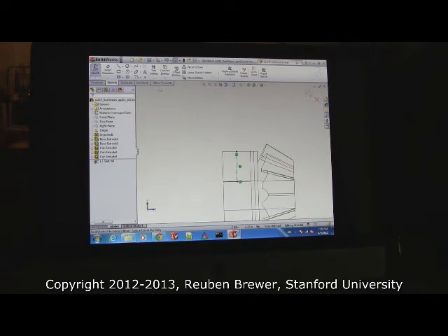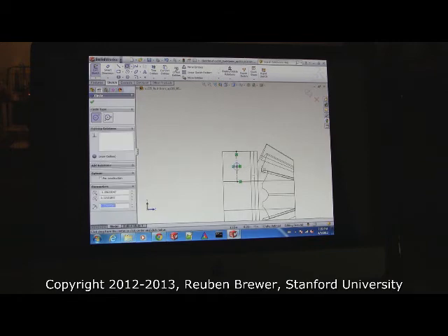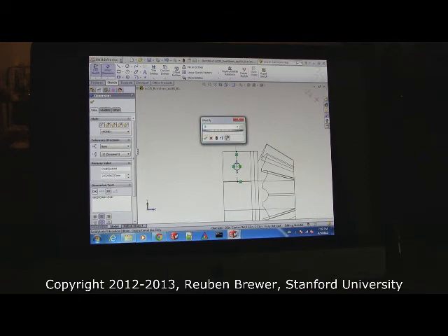Okay, now take a circle. Put it in the middle of that line. Watch my screen for a sec. You see how this goes directly on the middle of the line? That's how I can automatically resize the various diameters, and this hole will always stay dead center. And then the dimension on this one is 3.6.